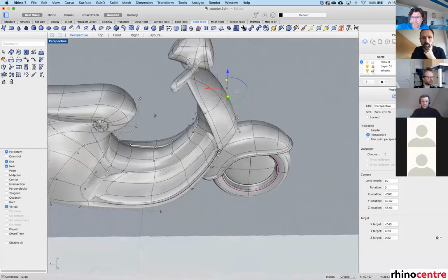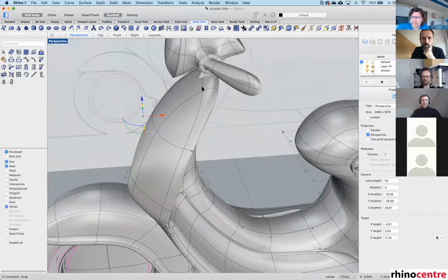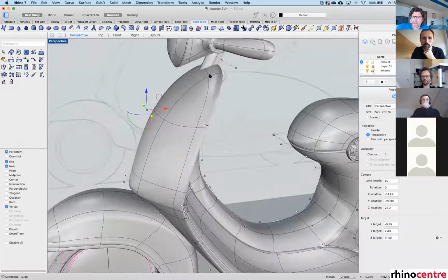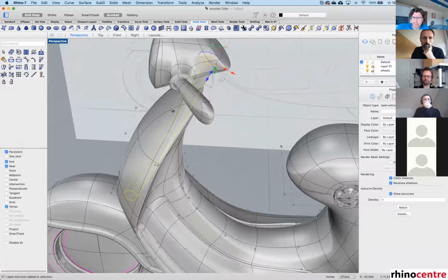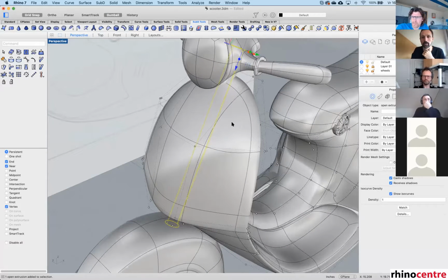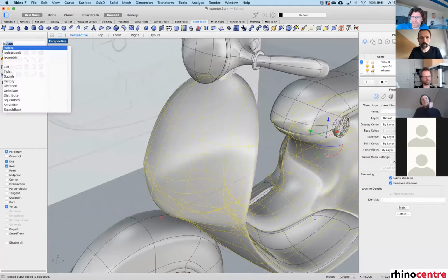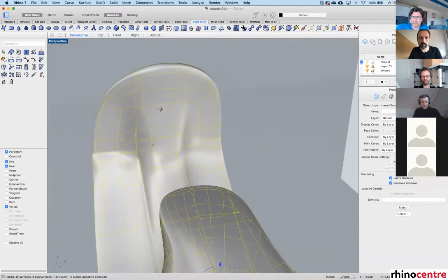So what might be a nice challenge here is to see if you can make an adjustment to this surface so that you create a hole where this steer goes into without having to convert it into a Nurbs model. For this, what you can use is the following tools. Let's isolate this one. So we want to create local detail there.